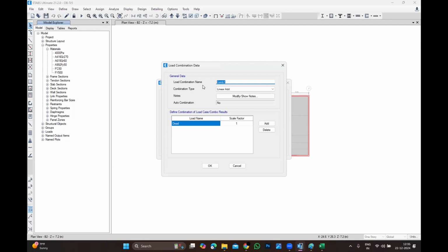Displacement you have on top. If you put a beam on the top floor, or two floors down, with surrounding beams, your displacement will be controlled because your maximum displacement is on top. Drift is not like that. Drift could be at two-thirds, or at three-quarters. So if I provided the beam on top, it will not be helpful, because from two-thirds onwards the drift might continue for 5 floors, then gradually reduce.